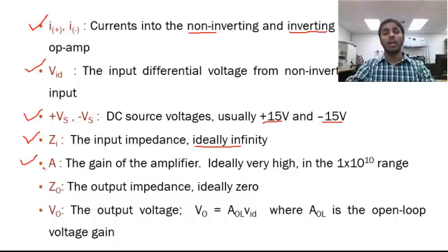So ideally the gain of an amplifier is infinite, but practically it's going to be very, very huge. And there are some applications of having an infinite voltage gain or very high voltage gain, but those applications are limited, which we talk about in open loop applications of an op-amp. Some of the applications use a comparator, meaning that if you want to compare two voltages, whichever is greater, less than, or equal to. Those are the applications that require a much higher gain.